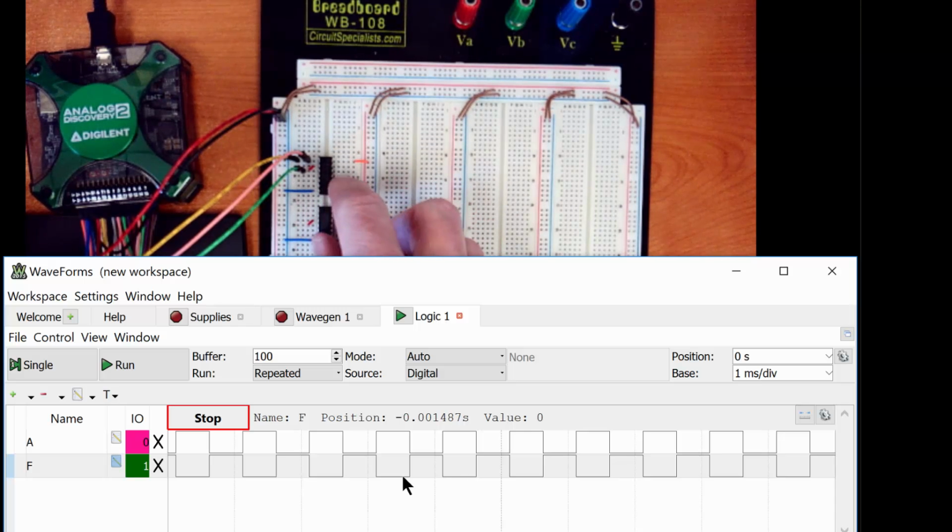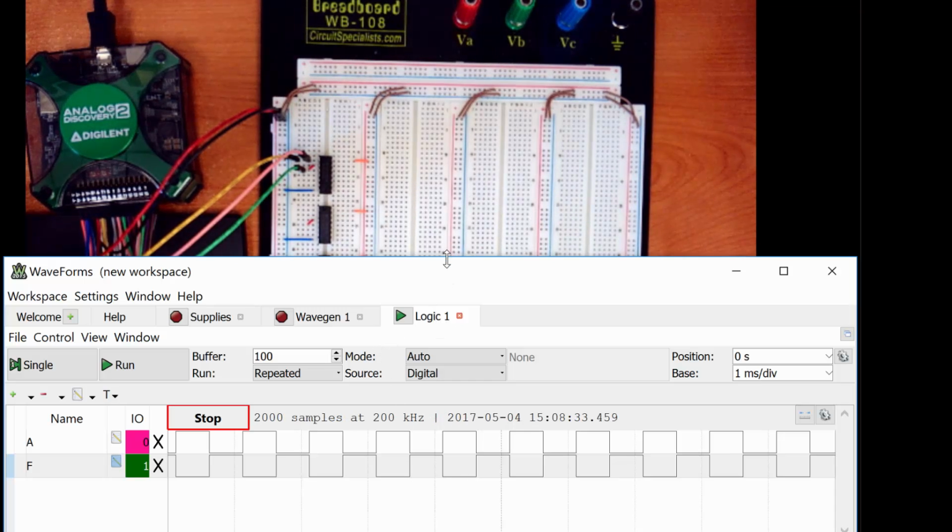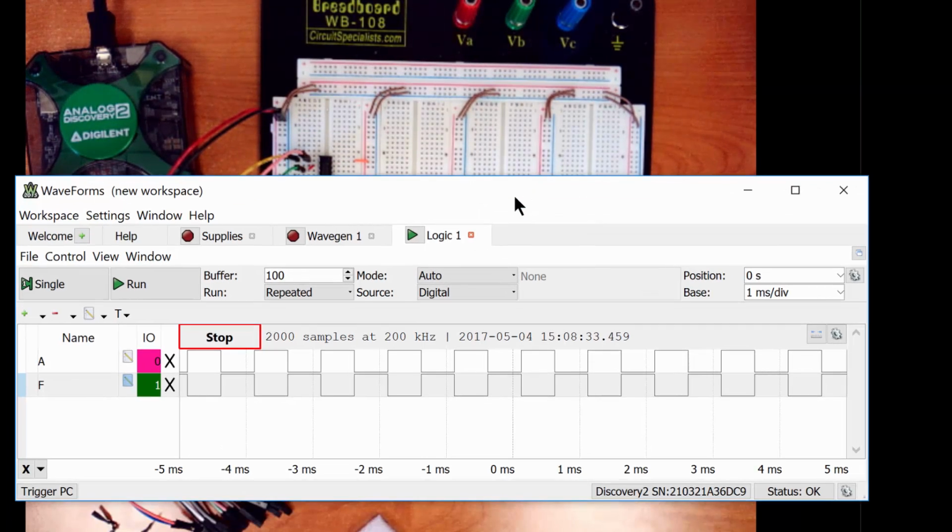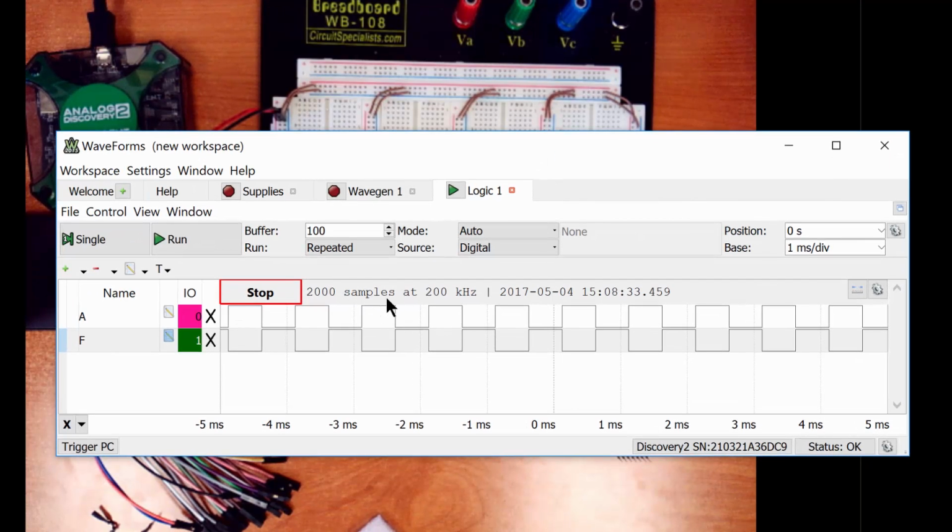What's cool about this inverter is that it didn't work without power, so we had to provide power and ground to it. That was the first step. Then we learned how to use the new tool of the Analog Discovery, and we just verified it. So first, you're going to take a screenshot of this for your records, and that demonstrates the operation of the inverter.